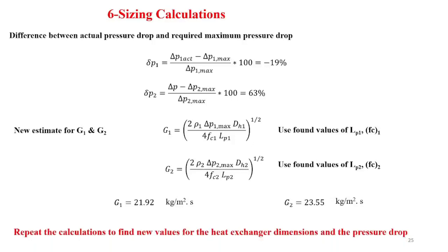Therefore, since the process is going to be lengthy, going through the calculation of the heat transfer coefficient, overall heat transfer coefficient, fin efficiency, and so forth, we have to use some kind of program to do these calculations. In our example, we have used a MATLAB program to do the calculations and find the design values for the heat exchanger dimensions.